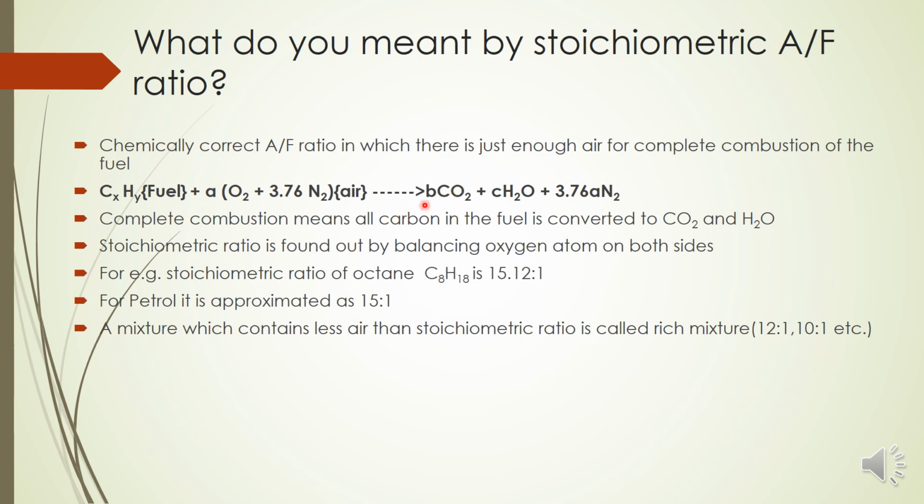So for a rich mixture, what will be the products? Any idea? As a rich mixture means we have insufficient air, complete combustion will not take place. So the products can have carbon monoxide also. Instead of carbon dioxide alone, we will have carbon monoxide. Similarly, not all the hydrogen atoms will be oxidized, so hydrogen also will be present.